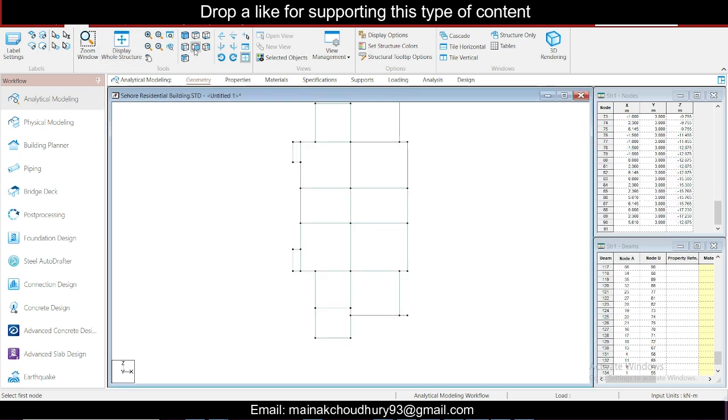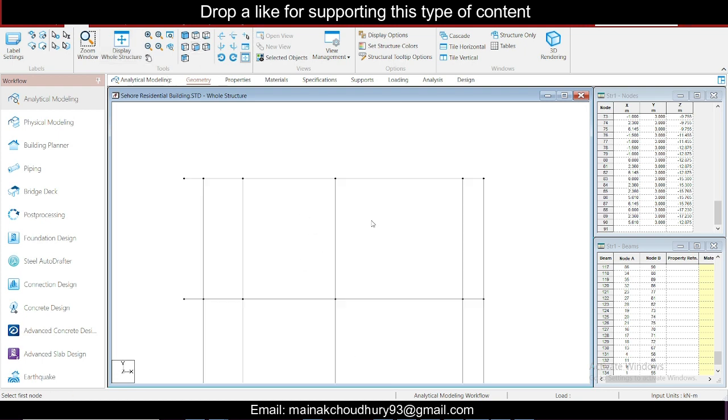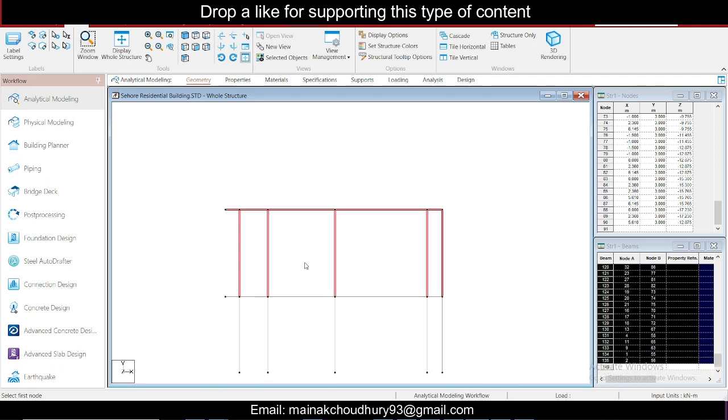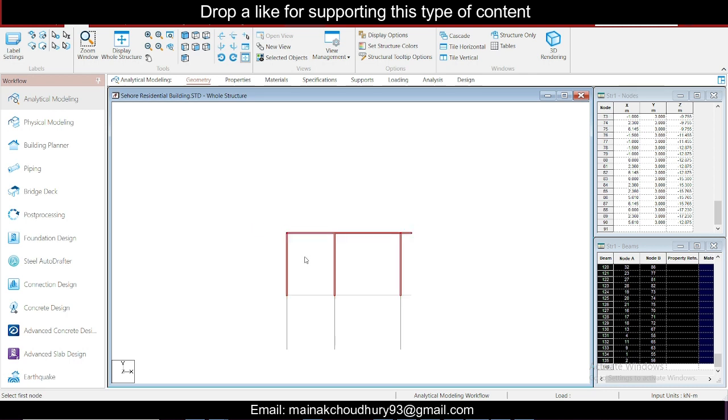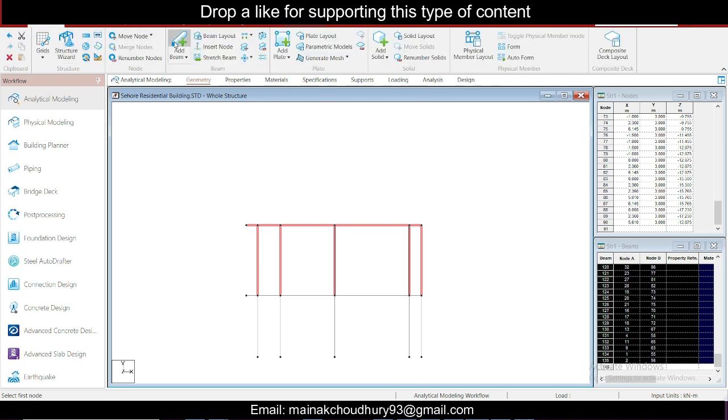So go to view, front view, display whole structure, front view again, escape, select this entire thing. Can I select the slab also in one go?